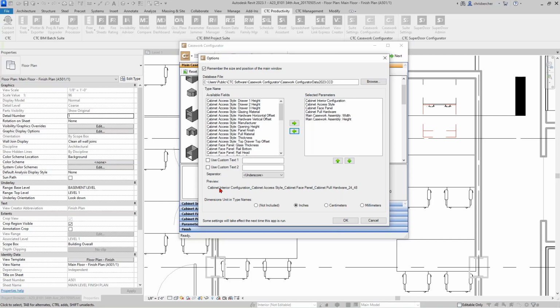That's awesome. But if I wanted to go ahead and pull in the seed name or a different name for these pieces here, I have to do a little bit of extra configurations on that. And I'll show you where that is in a second here. We're actually getting close to that. That's where I'm going next. But effectively, if you wanted to control how this is pulling and what it's pulling from, you just add, remove parameters from left to right, control the configurations however you want. Maybe you want the dimensions at the front of the name instead of at the back. Just, you get some up, down arrows. You can move things around and control exactly what the naming convention needs to be.